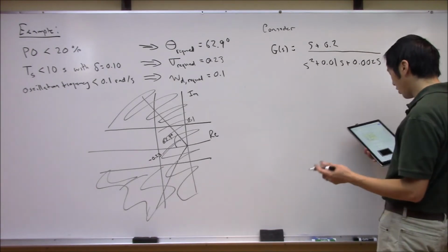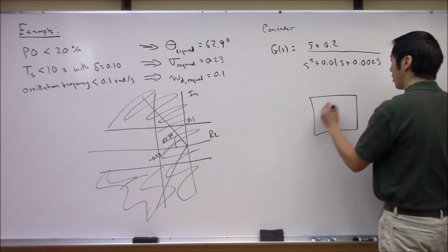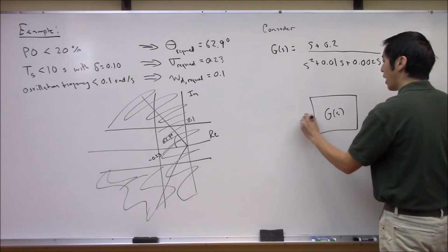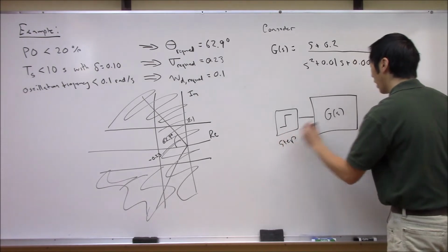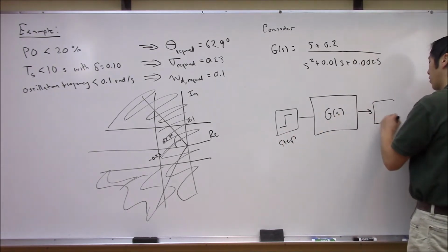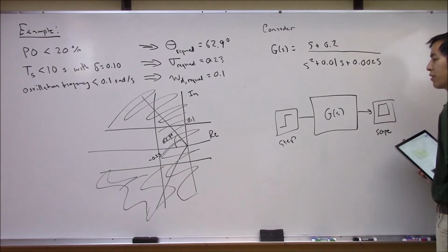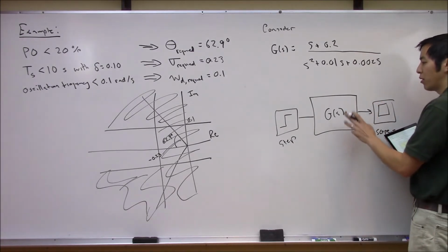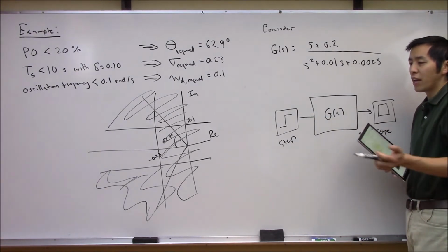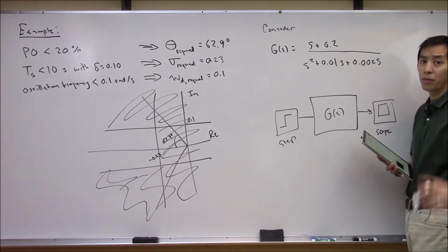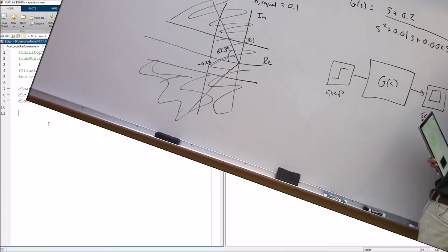So what I would suggest doing now is let's run over to MATLAB Simulink, make ourselves this G of S plant here, and just input a step function and read the response, right? Stick this into a scope of some sort. And let's just observe the signal here and see, does this system already behave according to what we need it to be? If so, we're basically done, and this will be one of the shortest videos I've ever done. All right, so let's jump over to MATLAB Simulink.